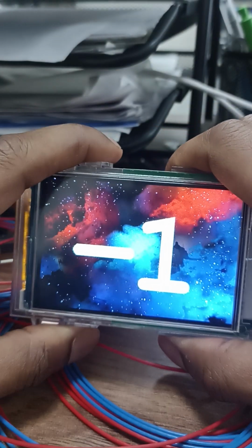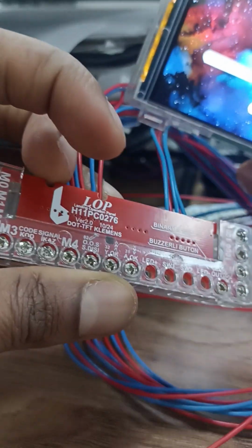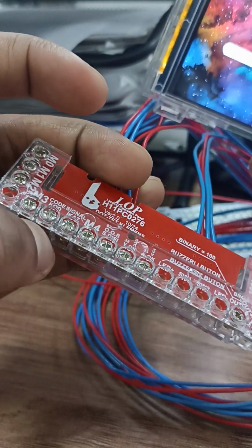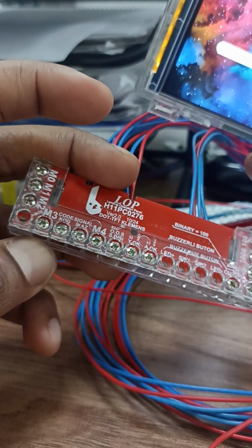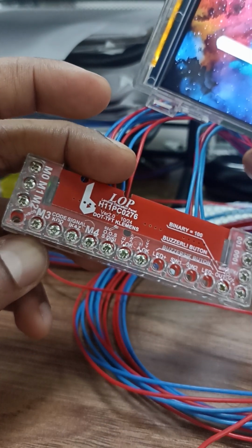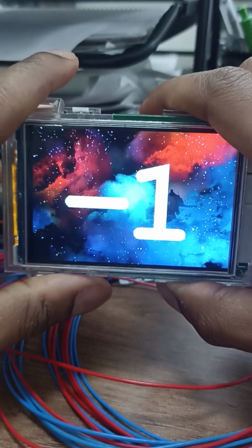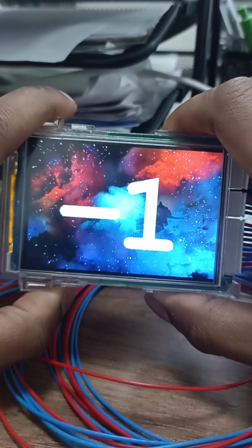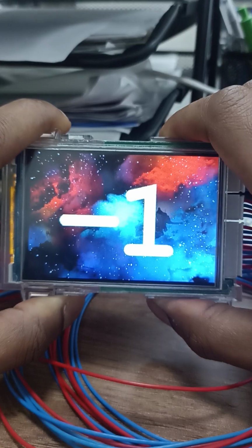It goes back to the first floor that is saved because we haven't connected to any control panel here. So the floor position information is going to be supplied using binary or gray code from the control panel. That is all when it comes to setting up the display, programming the labels of the display, the floor labels of the display.